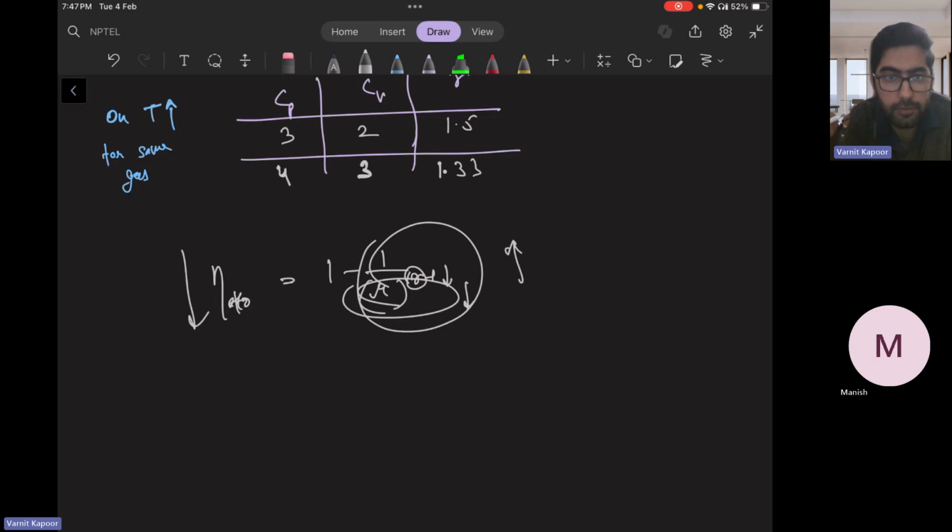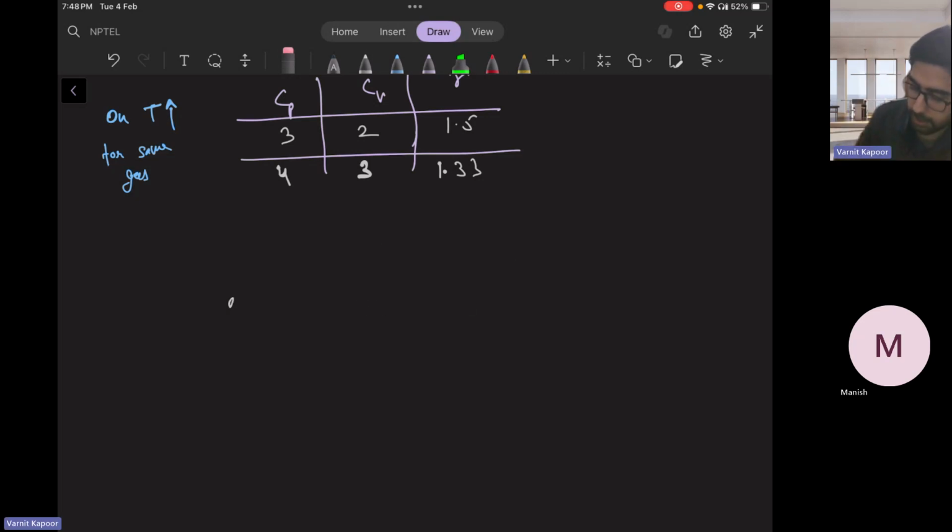And there are different processes if you see, compression stroke, expansion strokes. Okay. So when you observe that, in that scenario, theoretical, because these are theoretical cycles, you will say that Cp and Cv are said to be constant. Okay. But definitely there are temperature changes of the gas when you have an IC engine running. So Otto cycle is a theoretical cycle of an IC engine, very basic cycle. So temperature changes as per the process. So Cp and Cv should also change, but we are not taking those changes. We have made the assumption in our theory that Cp and Cv will be constant. Okay, anyways, this was to give some extra guidance on things.